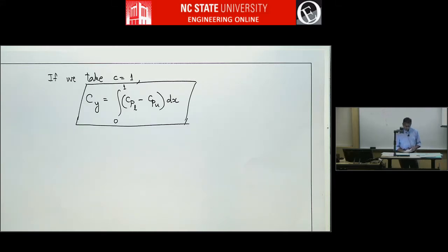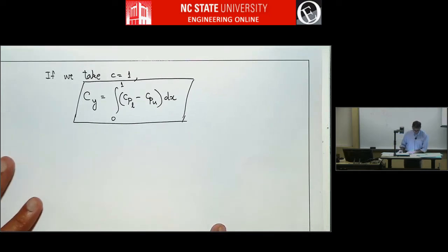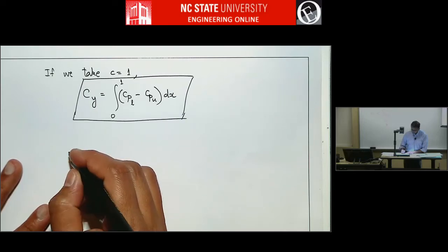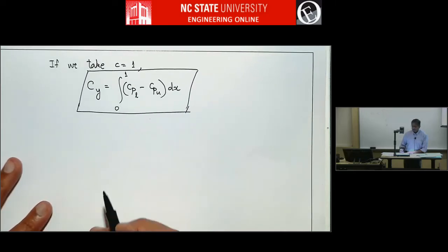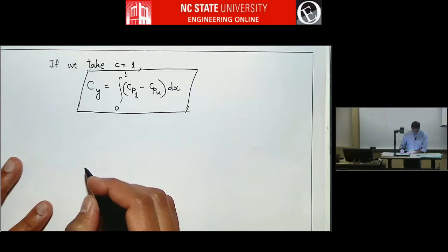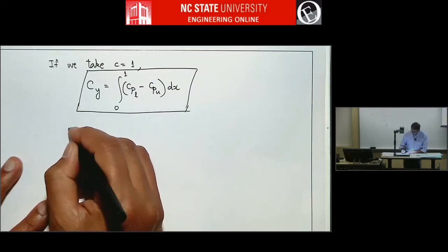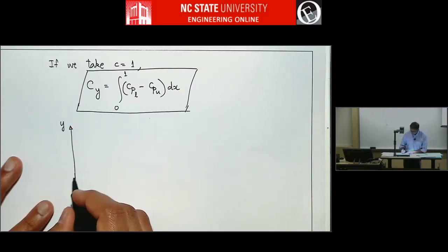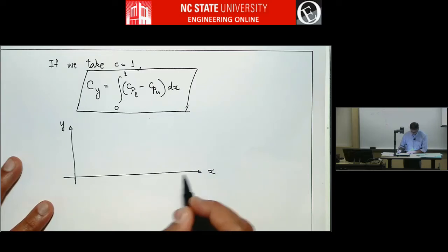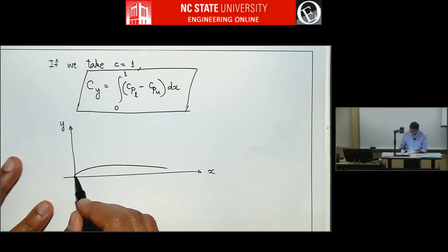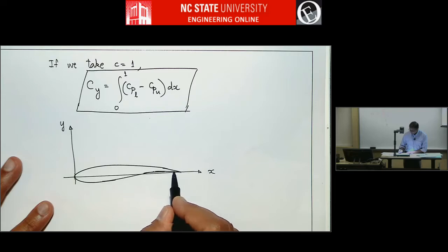So how does this connect to lift and drag? This actually turns out, cy is very similar to lift coefficient, because we're going to see that for small angles and typical flight conditions, this is practically the same as lift coefficient. So let's see why. We'll draw an airfoil and some typical lift and drag forces.